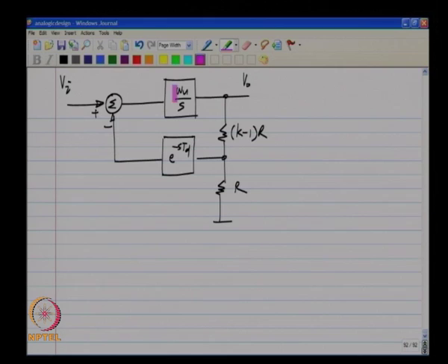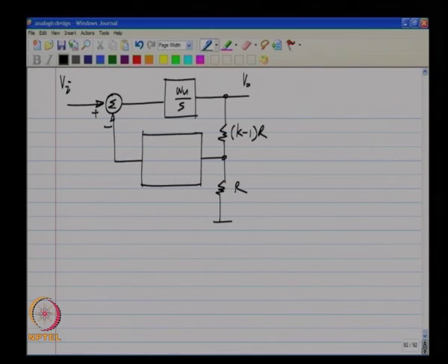Now, as I mentioned earlier, the poles and zeros come inside the realization of the integrator and in the divider and so on. But we can club the effect of all of that into poles and zeros in the feedback path. So, in general, in the feedback path we can have 1 plus s by z1, 1 plus s by z2 etcetera divided by 1 plus s by p1, p2 and similar other factors.